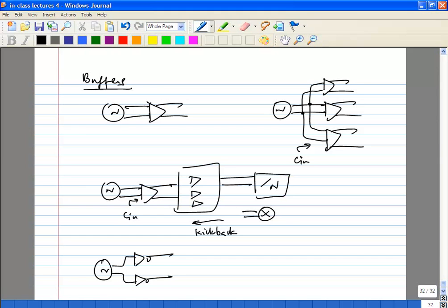Okay, we are going to come to that. Yes, you are right. Remember that the buffer typically limits your noise floor. We talked about that last class. If you consider just the tank alone, the VCO alone, whether you take 1 over f noise or thermal noise being injected into the tank, it always gives you either 1 over f cubed or 1 over f squared. So eventually you will hit a noise floor which is limited by your buffers, because otherwise you will always keep getting 1 over f squared.